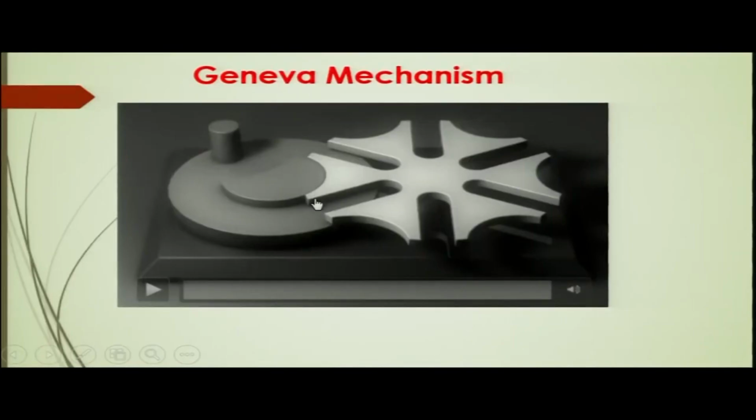Okay. Now, where can this kind of mechanism be used? Let us say we are having an automatic assembly. The table on which the automatic assembly is made has to index from one position to another position for positioning the sub assembly against the workhead on which the operation will be performed. When it comes to one particular position, it needs some time for the operation to be finished. That time is when the pin is rotating from one slot to another slot.